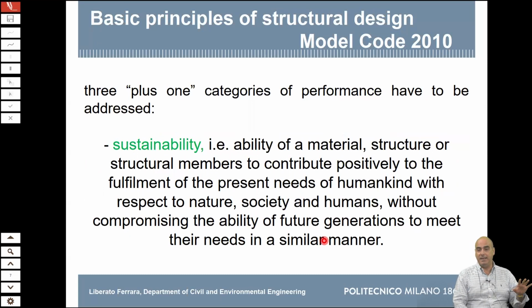We made a study, actually in Spain, where we were using a UHPC, or ultra high performance concrete, with very thin elements. The sustainability came from the fact that we reduced by 70% the quantity of material that we needed. We went from about a 9 to 10 centimeter thick slab to about 3.5 centimeter thick.